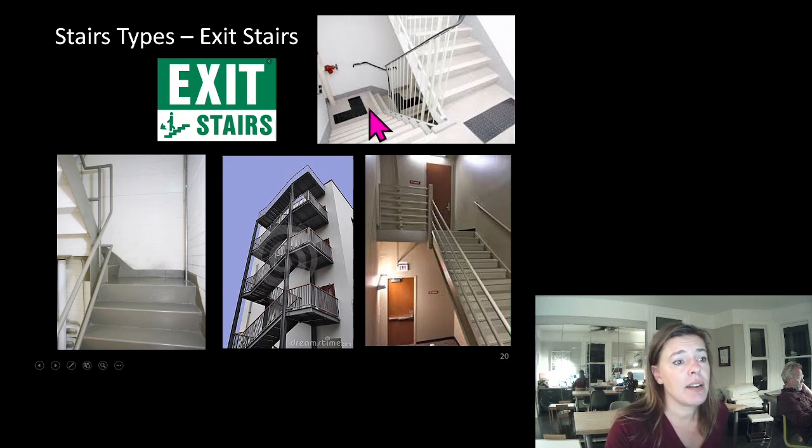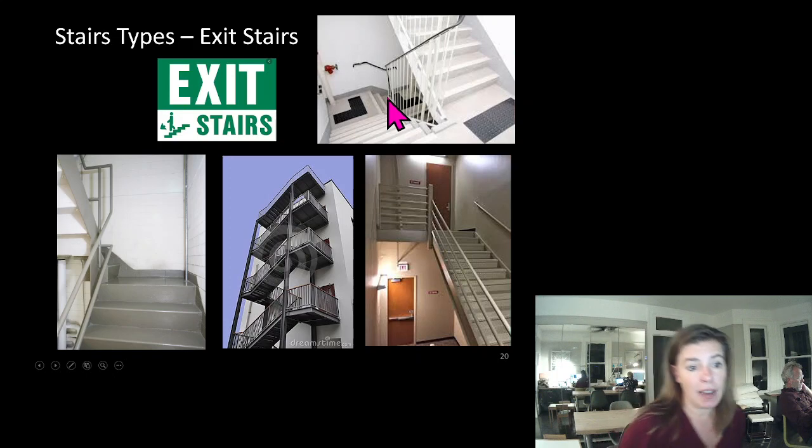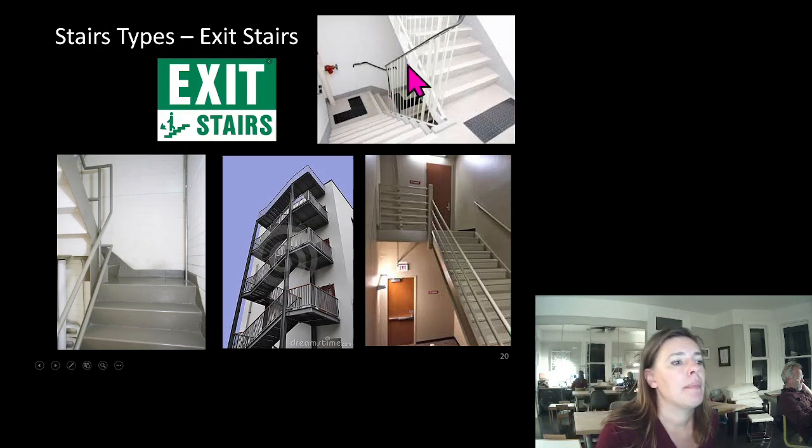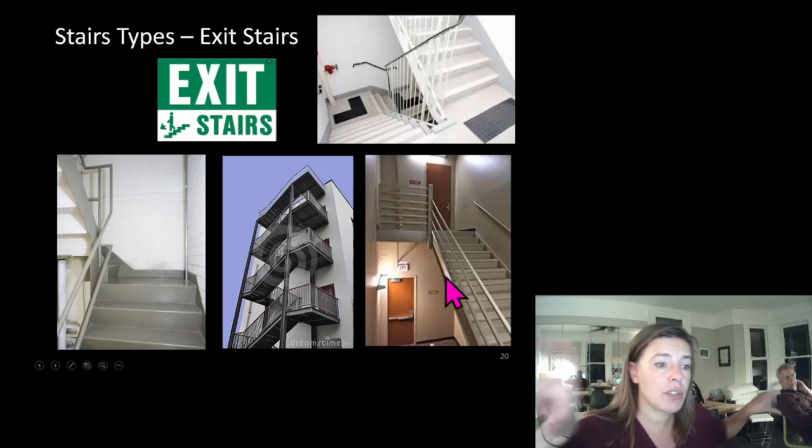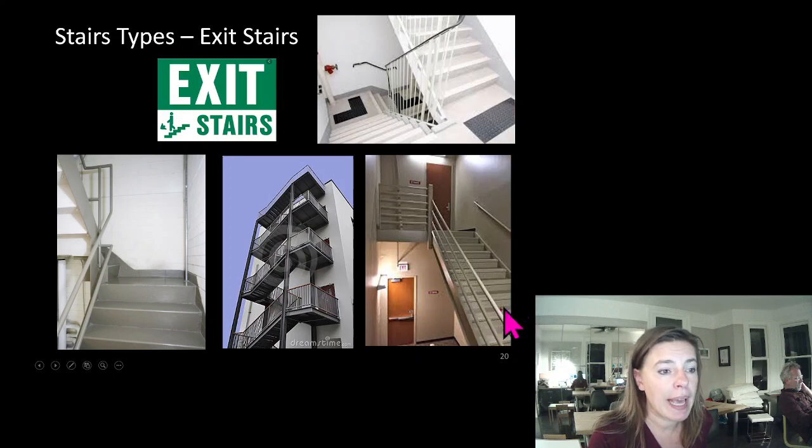Exit stairs. Exit stairs usually aren't as pretty. They're often tucked in a back room. They can be outside, and if they're outside, maybe you have the opportunity to start to get really beautiful with them. You can really see basic stair construction here. We've got our channels turned outwards. This was probably a metal pan with a concrete infill, a metal backer, and then they've put a finish on that, whether it's a rubber surface or not, I'm not sure. You can see this one looks like it's painted over, so I'm not sure if they put concrete in the pan or not here.